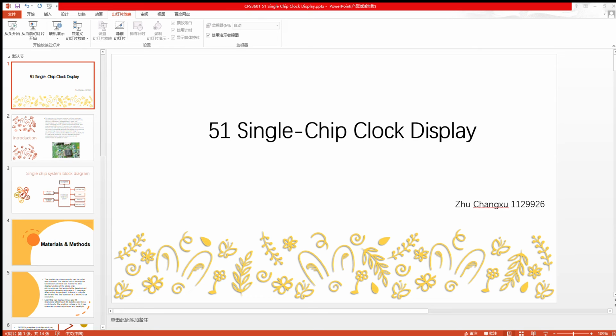The functions to be realized include writing data and reading data. The key processing module's functions include key scanning and key processing. The pressed key is detected by scanning the keys with the timer, and different methods are called according to the obtained key value.